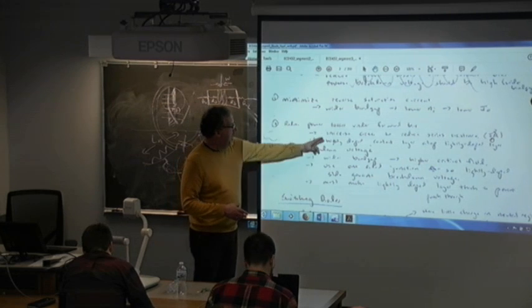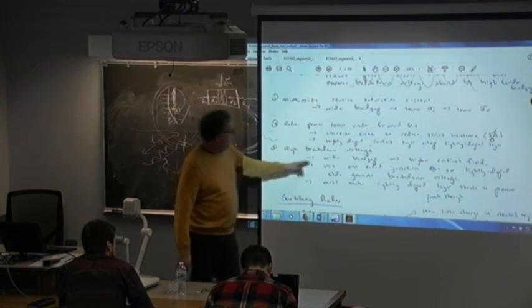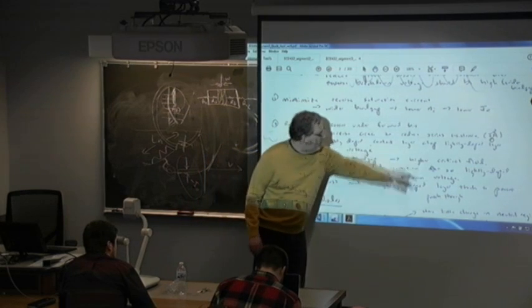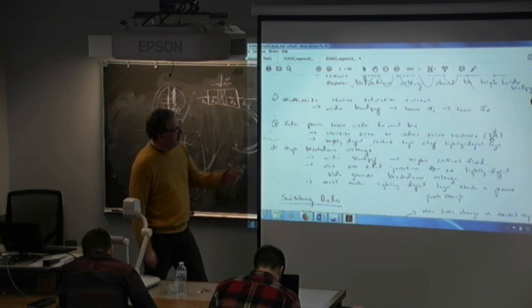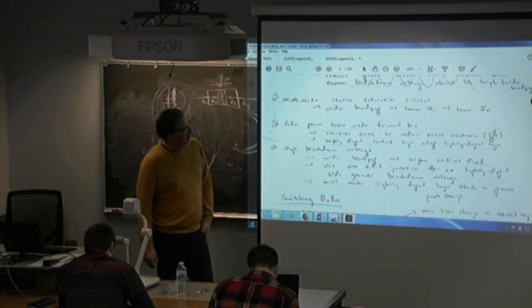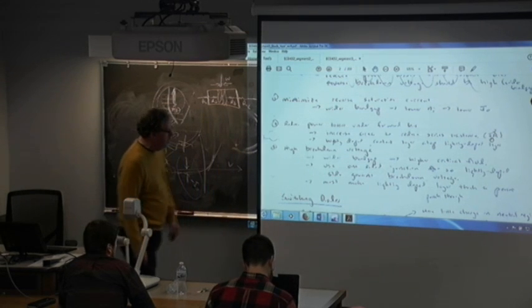A highly doped contact on top. I want high breakdown voltage, so I want wide bandgap material also there for that reason. High critical field. Maybe use a one-sided junction where the more lightly doped side governs the breakdown, so make that lightly doped.